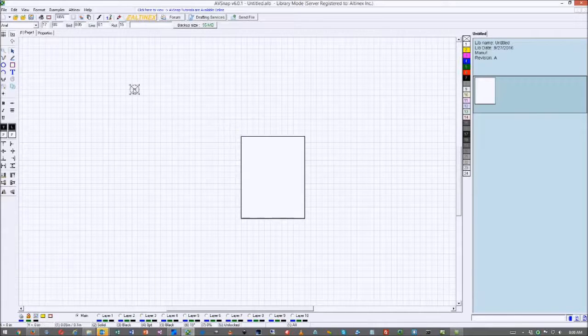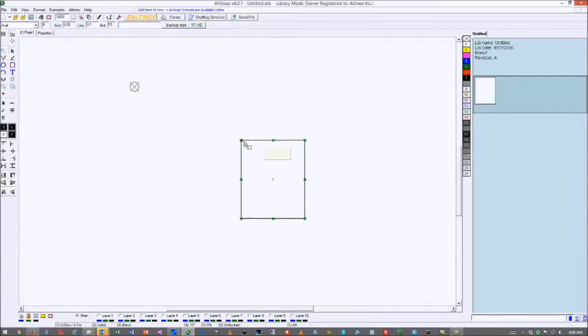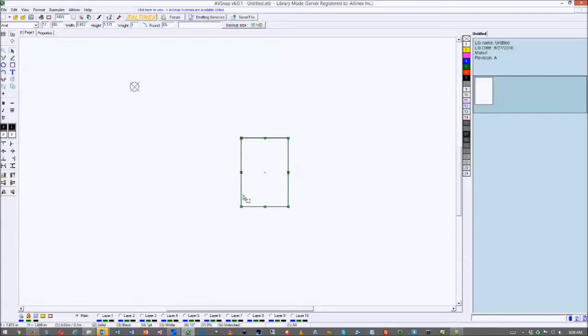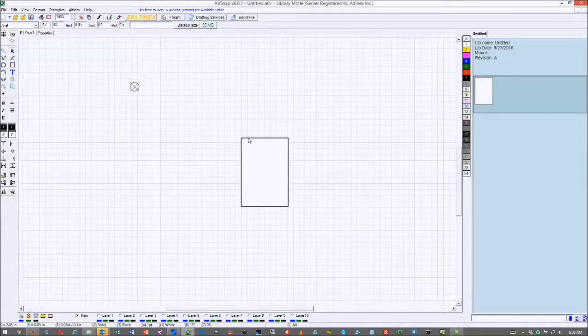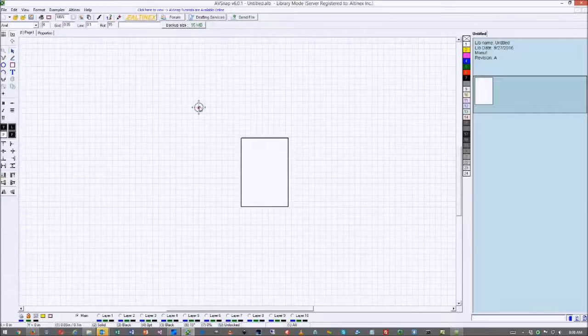The other way, let's say if you had a free drawing right here and you draw your component free, and then you say, well, wait a minute, I need to lock it to the grid. So turn the grid on, and you can see we're off grid right here. So one way you can do it is come to your origin symbol, double-click on it. When you double-click on it, it's going to move, and now you can move the whole grid.